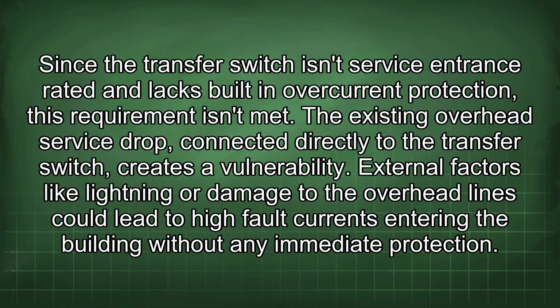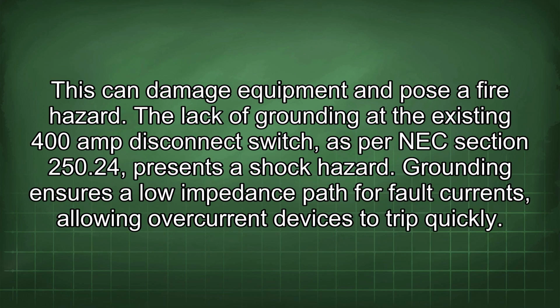The existing overhead service drop, connected directly to the transfer switch, creates a vulnerability. External factors like lightning or damage to the overhead lines could lead to high fault currents entering the building without any immediate protection. This can damage equipment and pose a fire hazard.